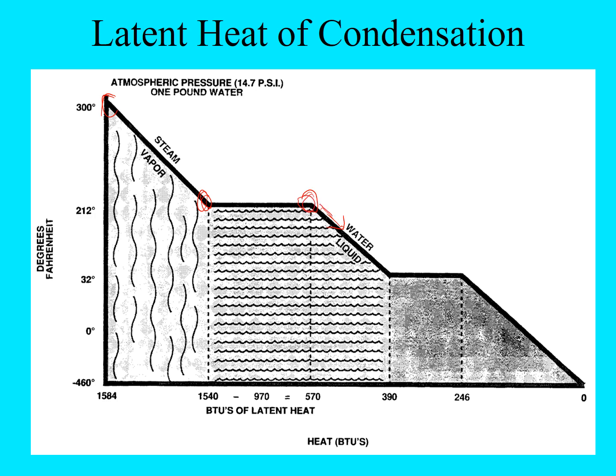liquid. Once we start dropping the temperature, this is what they refer to as subcooling. It's no longer a vapor. That pound of steam has condensed completely into 1 pound of water if we have a sensible heat change below 212 degrees Fahrenheit. So this is where we get into subcooling. We're going to cool that off until we get down to 32 degrees Fahrenheit. At that point, we'd have to remove 144 BTUs of latent heat.